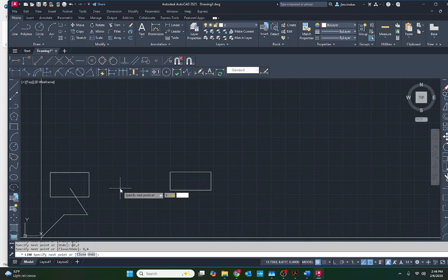and I type 5 comma, and this happens often. You make mistakes. If you make a mistake, all you have to do is type U. Actually, you won't go there. U for undo. Oh, I guess it will. We can type U, and U is the undo command. It'll undo the very last step that you were doing.